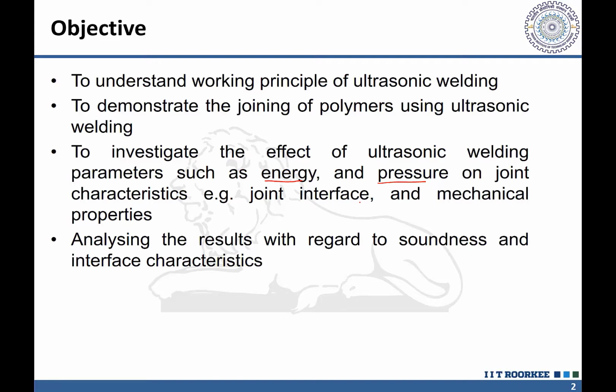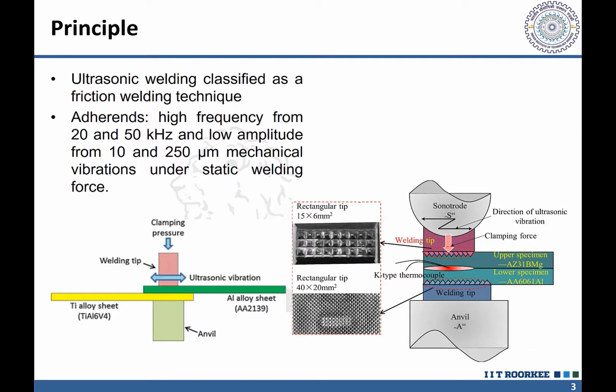Okay, so here if we see the working principle, this process basically depends on the frictional heat generated at the interface, and this interfacial frictional heat generation is realized by providing high frequency low amplitude mechanical vibrations.